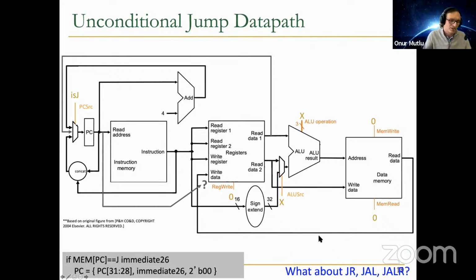Your book doesn't go into this much detail, but once you know the specification of the instruction, you can add anything you want to the data path to make sure that instruction is executed by the microarchitecture. Of course, you need to add the data path elements. You need to add the control signals as well.